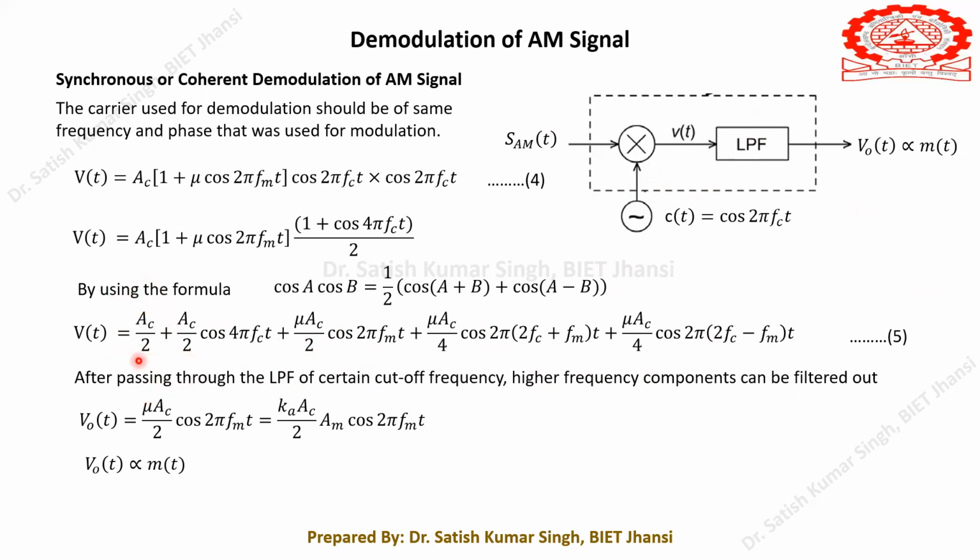For a DC component, its Fourier transform is delta f, which means we get another impulse at f equals 0, because it is a DC component. Its magnitude will be 1 if we are plotting the spectrum in the frequency domain. If the axis is chosen in omega, then it will be 2 pi delta omega.